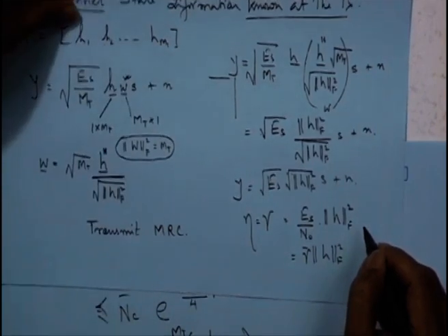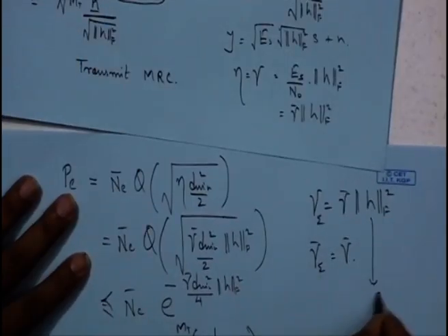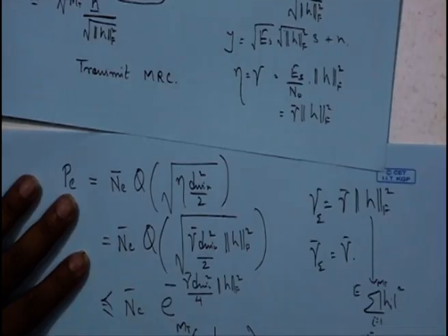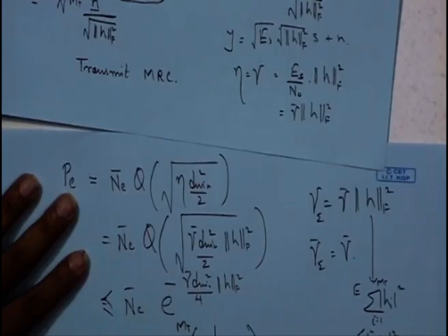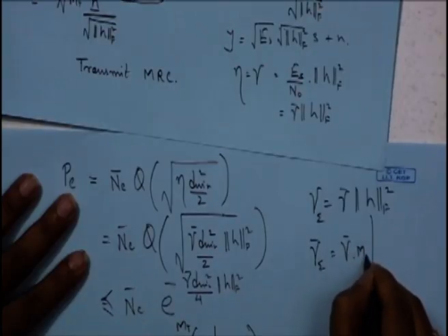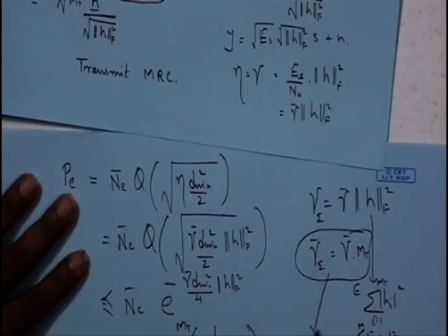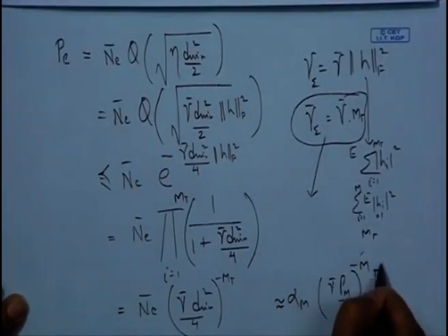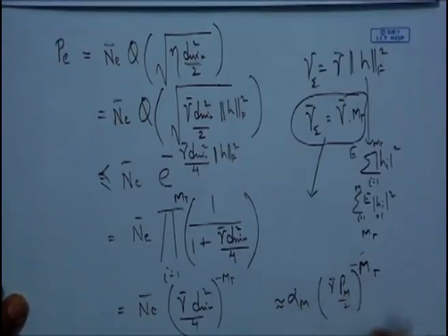So basically if you look at this, this is the sum over i equals 1 to Mt of |hi| squared, and there is an expectation. With the independence assumption, you have E of |hi| squared in a summation, and each of these is equal to 1, and this summation is from 1 to Mt. So together you're going to have Mt. So what you get is that there is an average increase in SNR, as well as this diversity gain of order Mt even in this scheme.